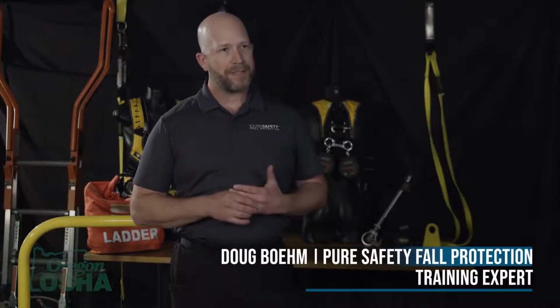When it comes to inspecting fall protection equipment, there are a lot of different aspects to it. Ultimately, you should always follow the manufacturer's recommendations or instructions on the frequency and what you're looking for that makes it a pass or a fail. General practice is that at minimum, according to the ANSI standards, which most equipment in today's manufacturing world is made to, is at minimum an annual basis.